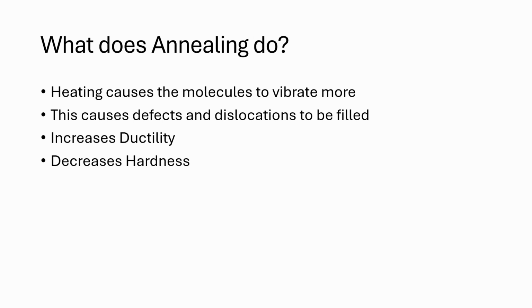What does annealing do? When annealing, the increase of heat causes the molecules to vibrate more. This increased energy causes them to move around, and the defects and dislocations to be filled back in. This then increases the ductility, but decreases the hardness that you gain from cold working.